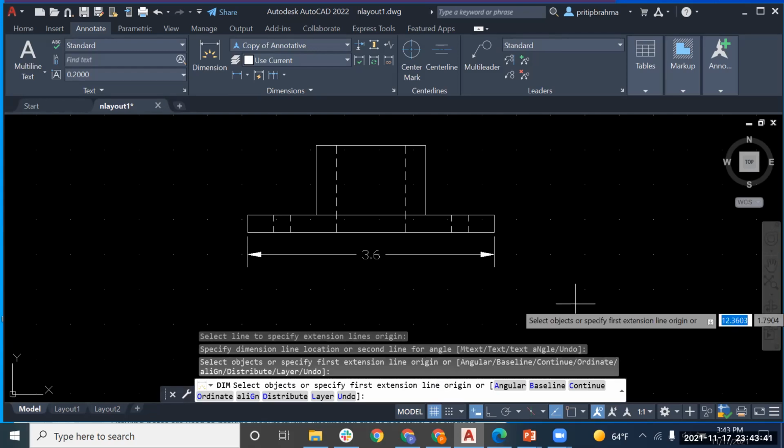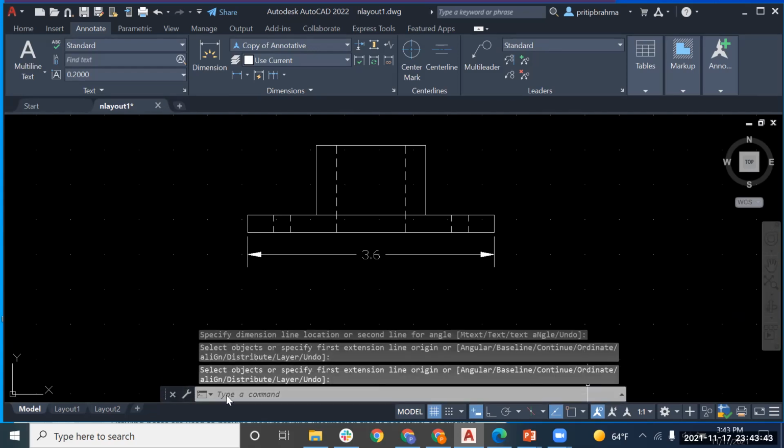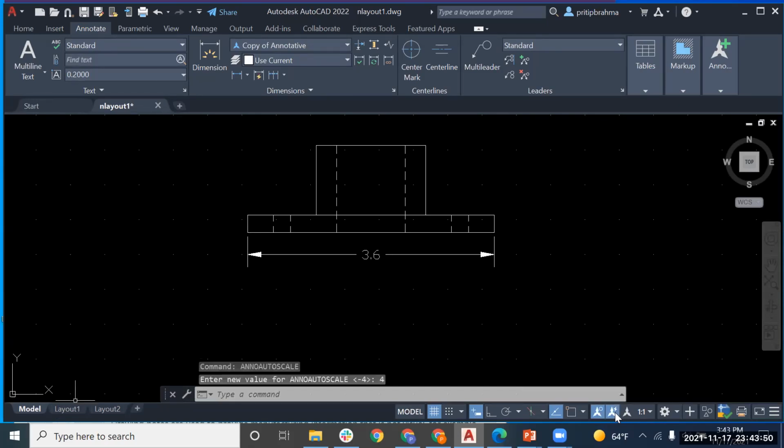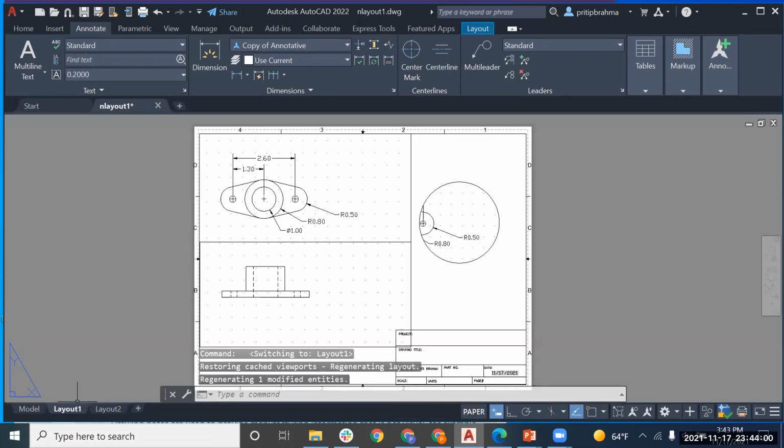Okay. So here we go. All right, there's that object dimension. Okay, now when we go to layout space, here we want to turn on add annotative scales. This is the button you want to turn on. And I might have had to do that before I added this. Let's see what happened here. Okay, so here, show annotation objects. If I click that on, it's now going to show this is an annotative object. And if I don't click it on, it's not going to show.